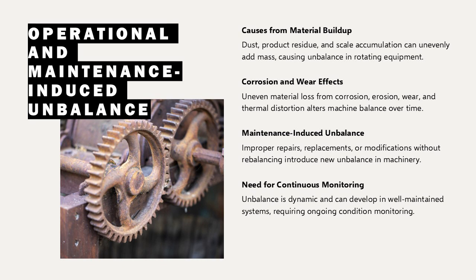Material buildup from dust, product residue, or scale is common in fans, blowers, and mixers. Corrosion and erosion remove material unevenly, particularly in pumps and turbines handling aggressive fluids. Deformation or thermal distortion can further contribute to unbalance over time.